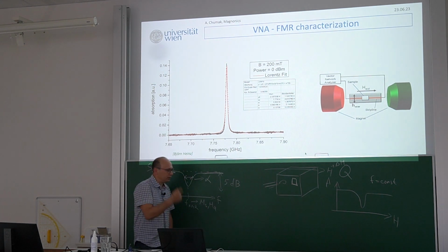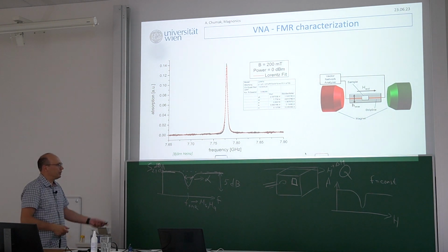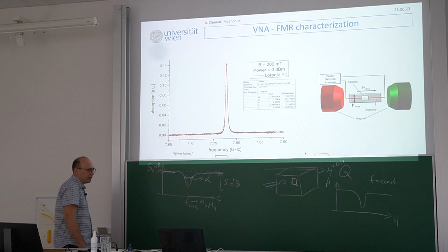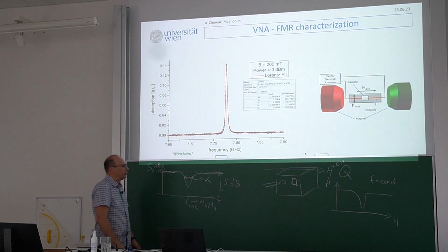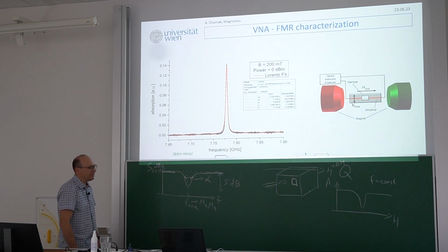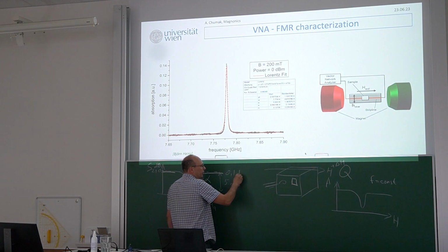Quite big absorption. Sometimes 10 dB. If you try hard, you can really have it as absorbers. That's what people think about, we're designing stop band filters based on this approach. If you're working with nanometer thick YIG, then this will be maybe 0.1 dB.